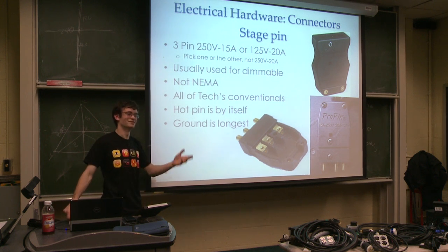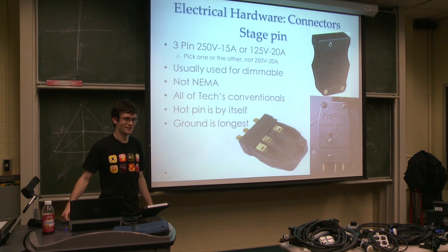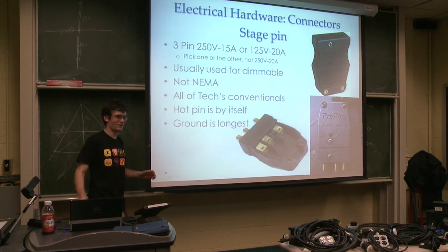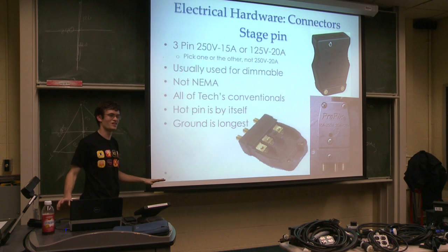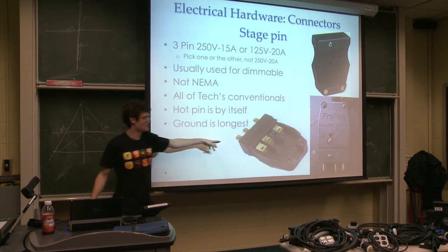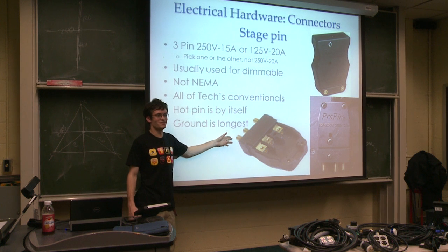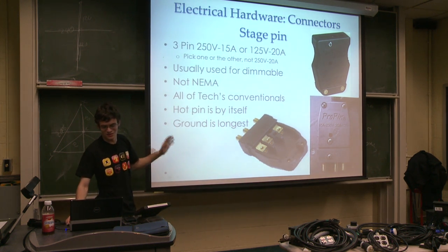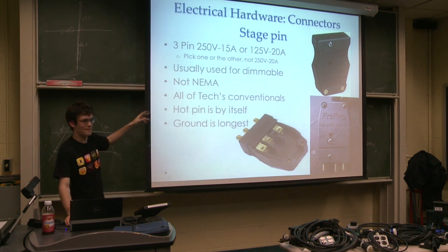It might also mean someone got a different cover. So if there is some kind of standard, know what that standard is, and don't assume that if you go to a random place that any kind of convention is followed. If you see something, always ask. For example, this connector: ask whether it's dim or non-dim, whether it's 120 or 250. If you just see a line hanging somewhere, don't assume things.